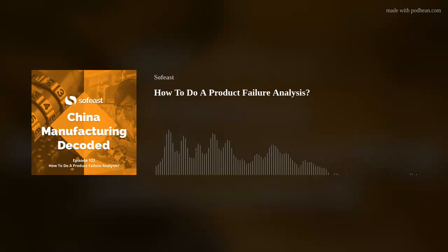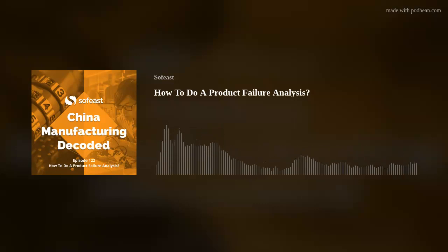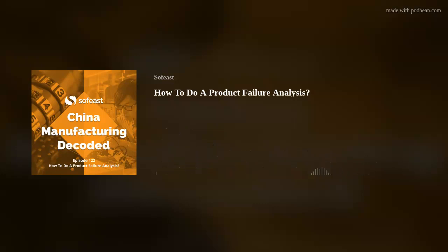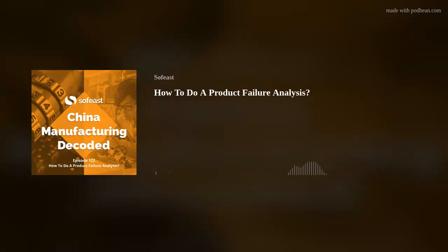Yes and no. It's possible to apply a typical corrective action plan template, but it's really not that great. Or doing an 8D, the number 8, eight disciplines, which is a good one especially when there's an escape of some kind of defect in manufacturing. We like the 8D, again, it is very structured, but I usually do not apply it for a failure analysis. It's better to have another kind of approach.